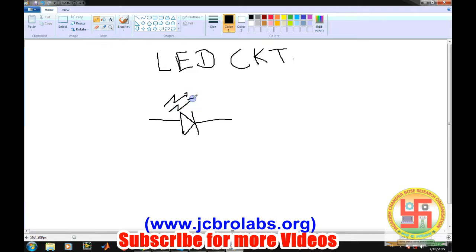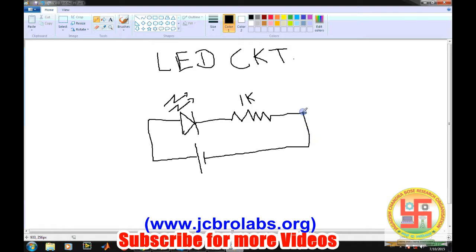It is a special kind of diode which emits light, and we will connect a resistance in series with it, normally a 1k resistance, so that it restricts the amount of current flowing through the circuit. And then we will connect it to the +5 power supply. So this is a small circuit which we will implement on the breadboard. Let's have a look at how to implement it.